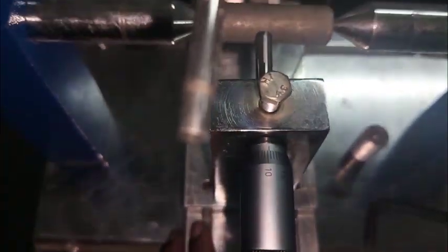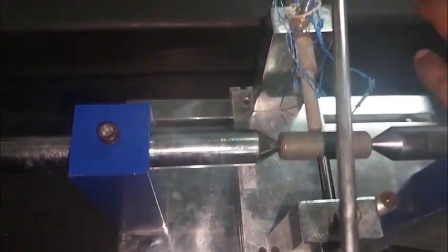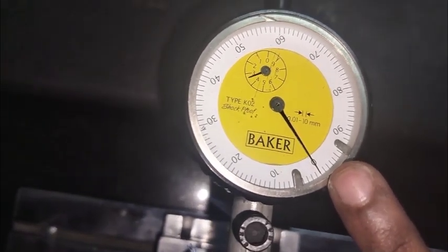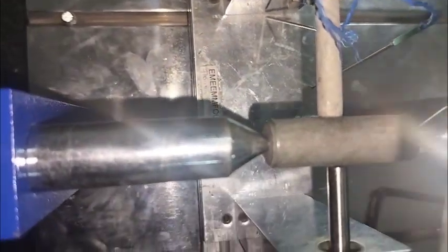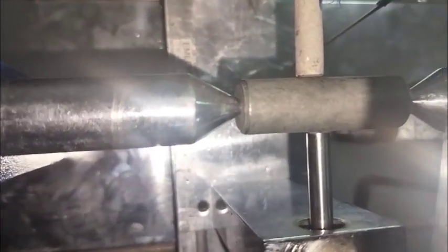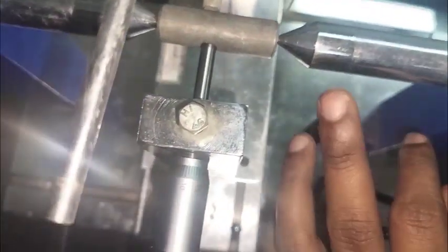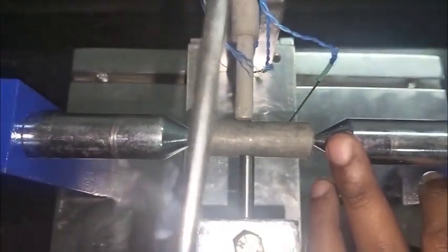Now we can move to the procedure of this experiment. First, the indicating pressure gauge is set to 0, using the initial adjustment. Then the specimen is placed between two centers. The standard dimensions and the corresponding values are noted. Then the thread plug gauge is placed between two centers for measuring effective, major and minor diameter. Simultaneously, the thread workpiece is first measured by placing it between two centers.